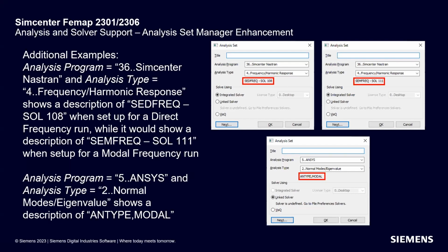You can also, if you have the ability to access enterprise Nastran, whether it's through tokens or just through a license server, use the integrated solver here, and you can say license type and change this to enterprise.